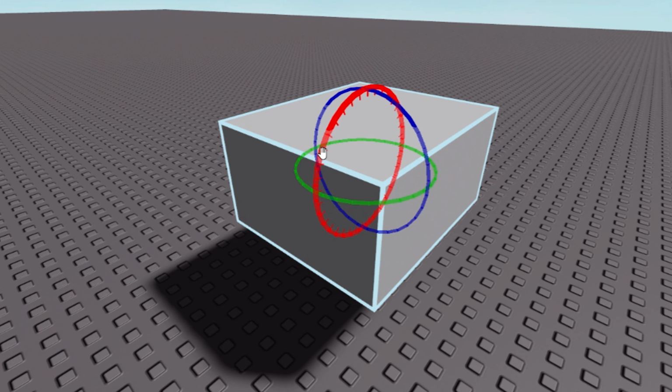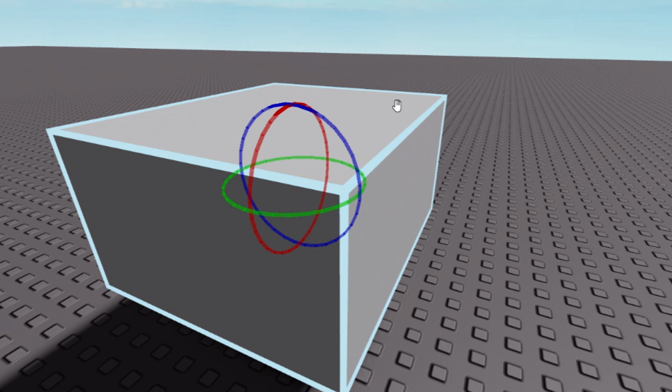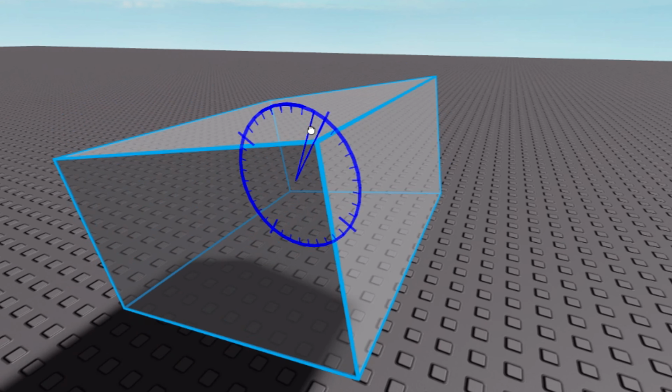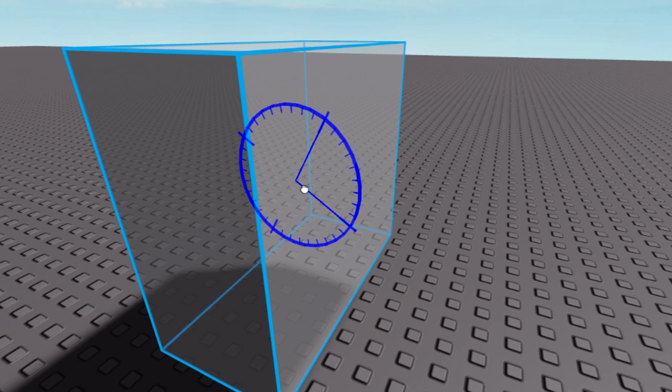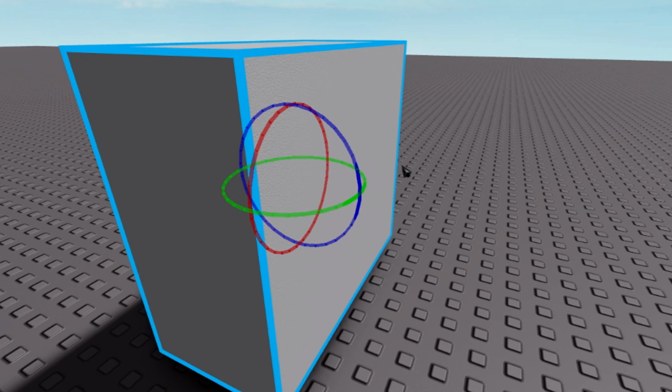The Rotate tool lets you rotate objects around. Similar to the Scale and Move tool, it displays 3 axes, but instead of handles, it displays them in a circular fashion. Selecting a handle will display a clock-like circle and will let you rotate the object in the selected axes. The large lines represent 90-degree turns, and the small lines represent 10-degree turns. The shortcut for rotating 90 degrees is Ctrl-R.